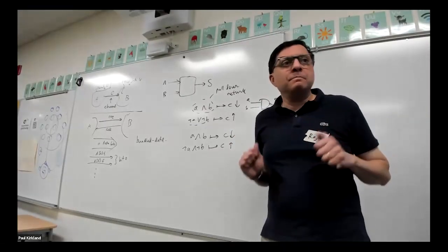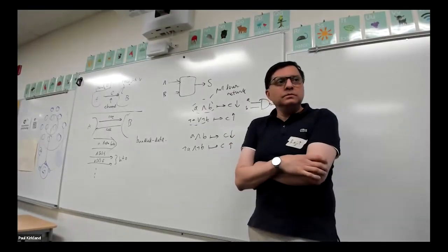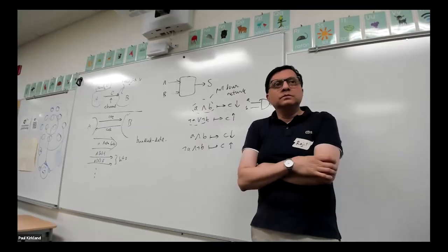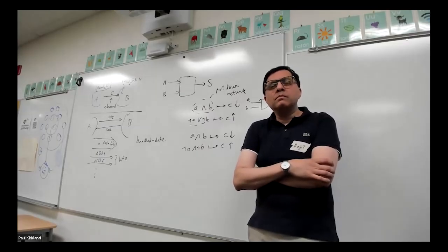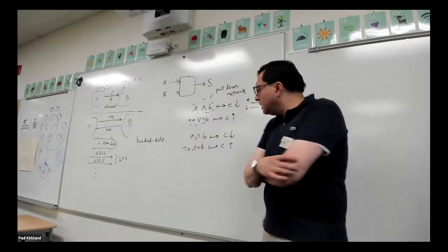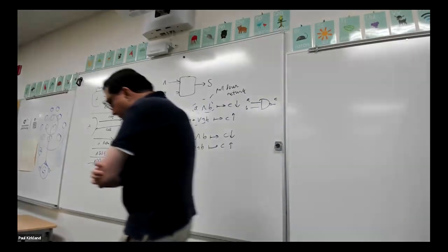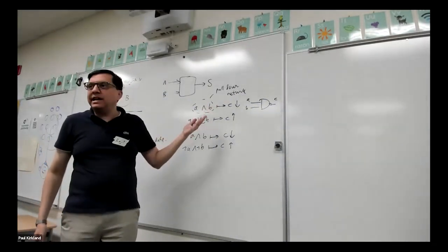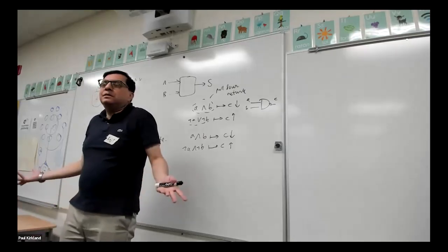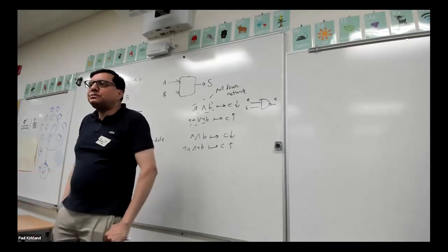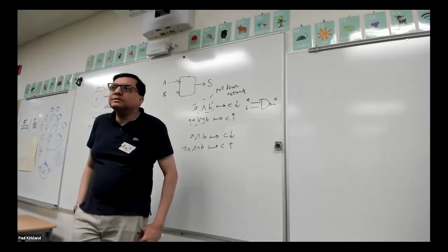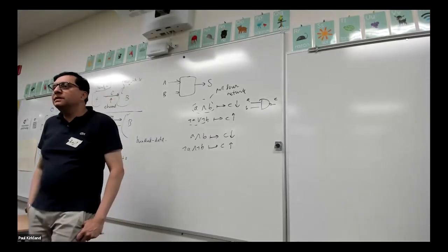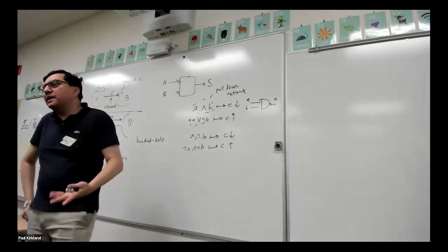Yes. I think it makes sense to me, on the level of pull-up network, like you build your own gates. Yep. But this is not compatible with normal static gates, right? You cannot use the standard AND gate. Well, I mean, if you get a standard AND gate, you can use it. Okay, so there is stuff that we can express here that will not be part of a standard cell library, correct? Yes, the C element. That's right. Yes, this is richer than what you can get in a standard library.